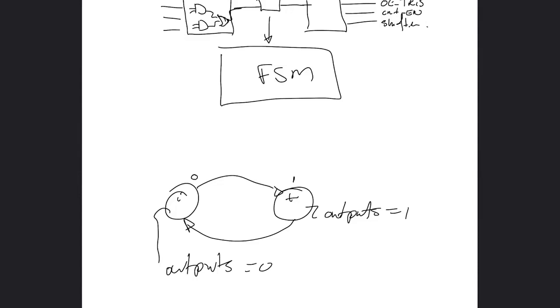We only have 2 states, so we only have to enumerate for a single bit, which means that this flip-flop is only 1 bit, it's only 1 flip-flop. It also means that the output logic is literally the same as the state. So over here, you'll just have a wire that connects it. There's no logic; it's essentially just equal to. So there are no AND gates or OR gates or NOT gates. There's no silicon required.